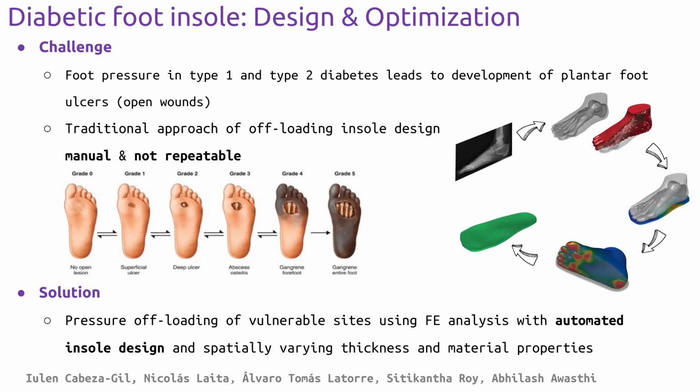One usual solution for this pathology is the development of a foot insole that redistributes the stresses and the contact at the foot sole, in order to decrease the contact at the areas where the bone is closer to the skin, that would be the frontal part of the foot and the heel area, and to increase the contact in the center part of the foot, which has more soft tissue.